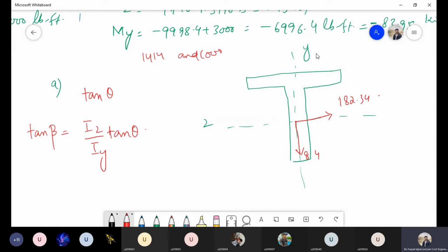Due to these loads, I have figured out the two components on the principal axis, and based on these two loads, there will be a final resultant moment, right? So the angle of that resultant moment, from the horizontal principal axis to this resultant moment, will be my angle theta. Because if you remember our initial derivation for inclination, the angle theta was the inclination of the final resultant moment with respect to the horizontal principal axis.